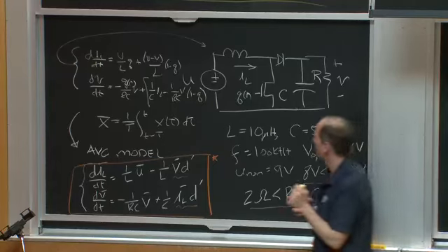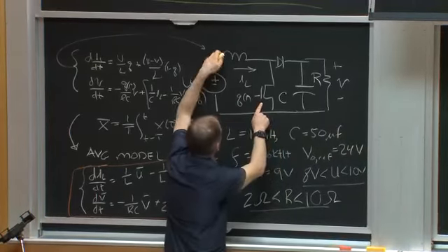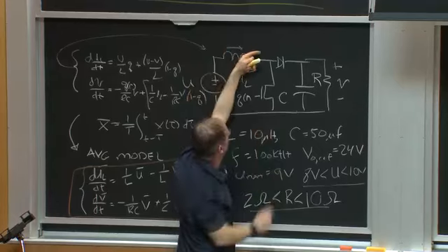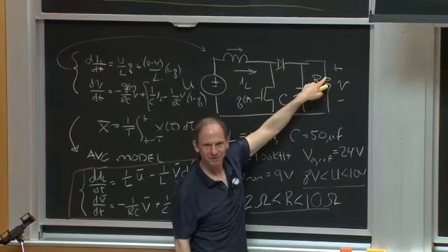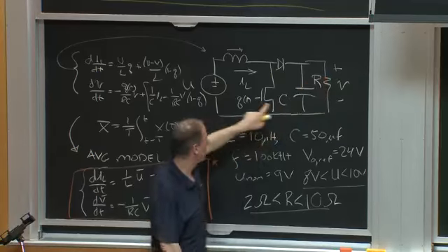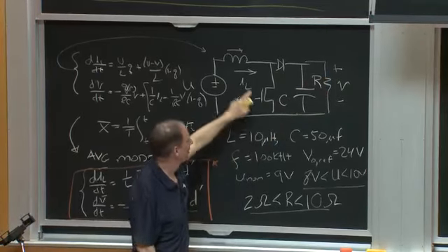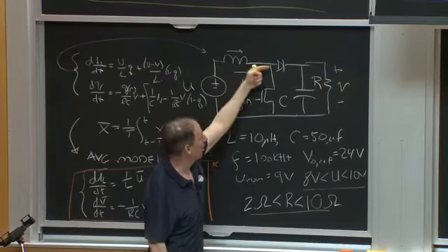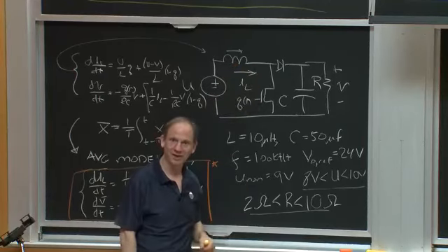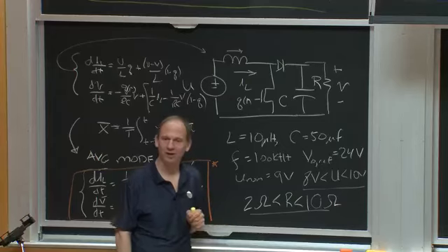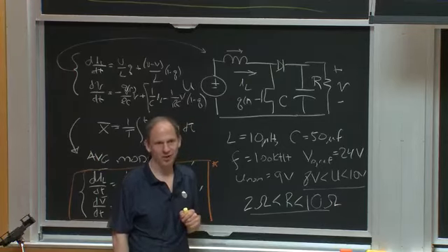Okay? Well, so I was running at 50%. Whatever's in my inductor current, half the time is going to the output, and that's what's supplying the resistor. Suddenly, I increase the duty ratio. Now suddenly, instead of going to the output half the time, the inductor current's going to ground half the time. So suddenly there's less current feeding the output. And so what's the output voltage going to do?